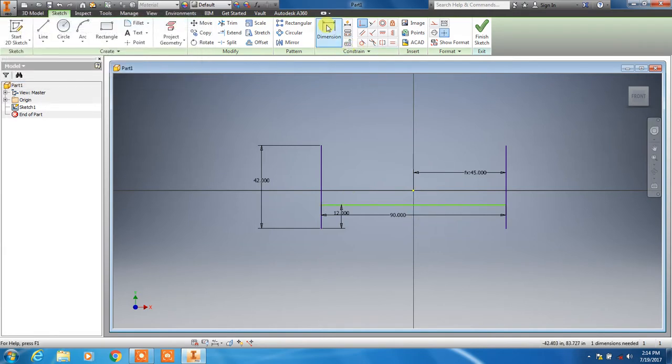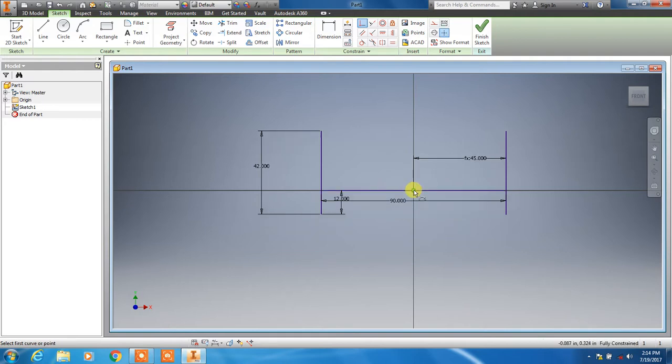Let's see what happened here. Sometimes, okay, so I want it to go from there to there and constrain those two lines together. Alright, let's see here. Coincident constraint from there to this dot. Okay, there we go. I don't know what was wrong. Sometimes it does some stupid things. I know it couldn't have been me, but anyway.